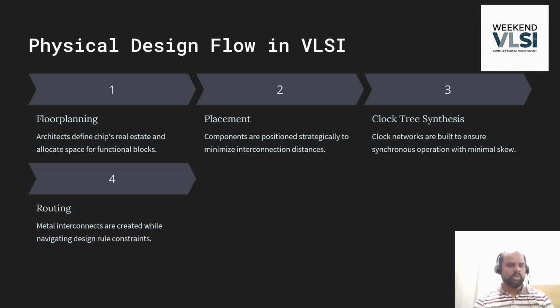Next is routing. Okay. What does routing do? Routing is where actual routes for the data path are done. Why do we do this? Okay, we want the actual RC for these structures. Earlier, it is just an estimation we do, either from the virtual route, as I said, right, or global route, where we only define the G cells and what the congestion is for the G cells. We estimate how many routes the G cells can handle. But now, when the routes are there, that is where your crosstalk will come into the picture, or your cross coupling will come into the picture, because between two routes there will be some spacing.